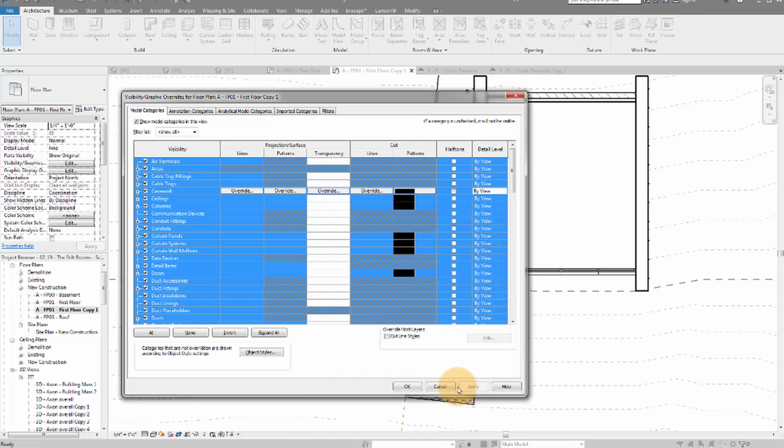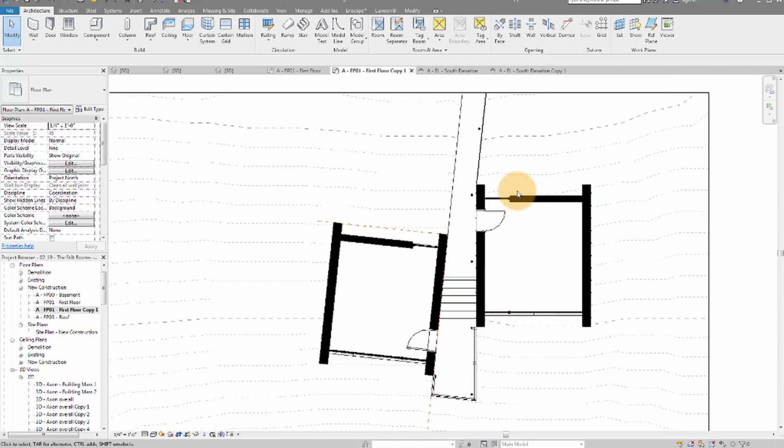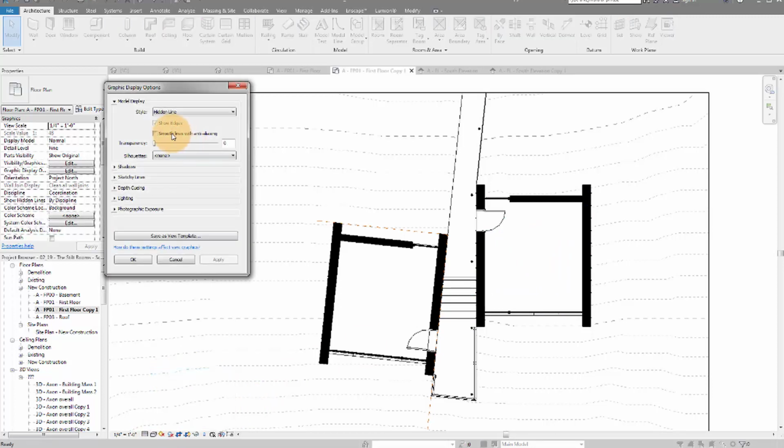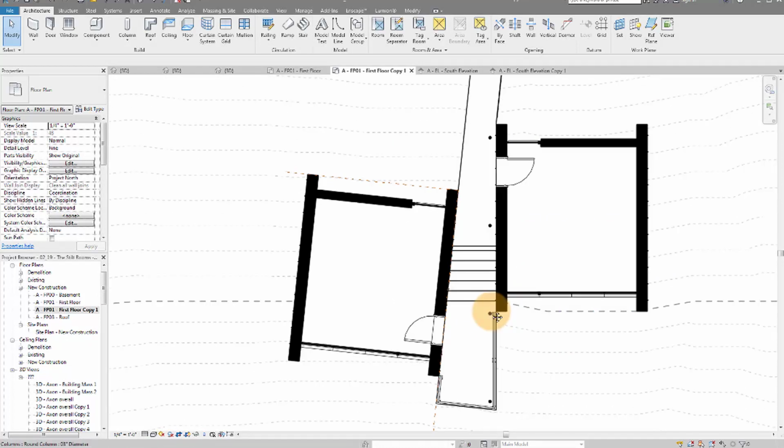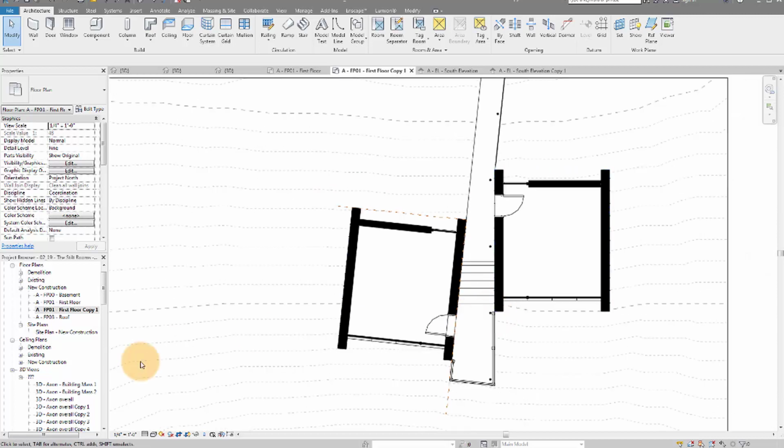Click OK, OK, apply, and OK. And there we go. So automatically we're already getting some depth to it. The other thing that I always do is I turn on anti-aliasing, which really helps smooth out your images. And then I apply what I call the 70-50-20 rule, which has to do with ambient shadows, lighting, and so on and so forth. And so that's what you get.